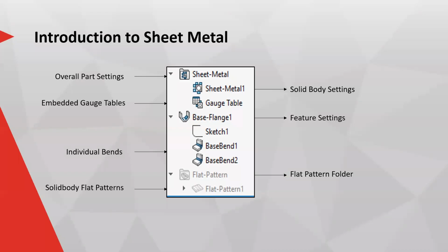So that's what I meant by depth. From there, we can also override sheet metal parameters and your bend radiuses. We can also change our K factors, stuff like that. Then again, SolidWorks, to create the flat patterns, needs to create individual bends. So if I create a complex part, I'll have more base bend lines. And if I create a simple part like this one that I use, for example, there are only 2 bends.